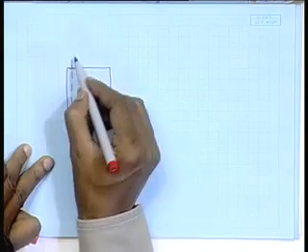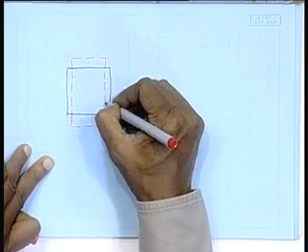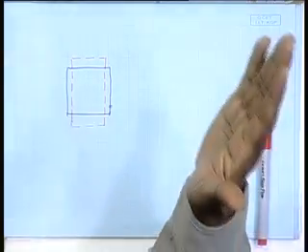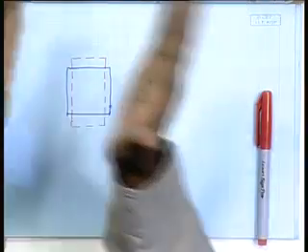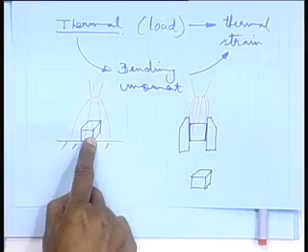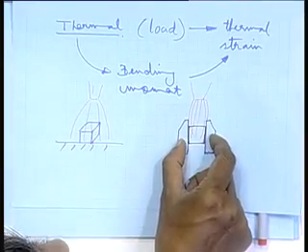This dotted line is the changed shape. Obviously, I am drawing it a little exaggerated. This means in the breadth, it has shrunk, and now there should be conservation of volume, so it has increased in this direction. That has happened here, whereas it has not happened there. So, that means this vise had some role to play.